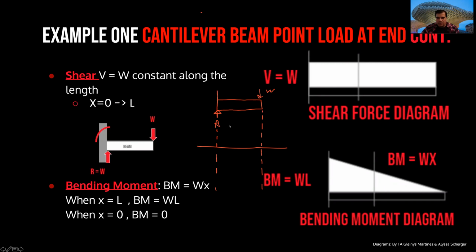And how will the shear force be? Well, if this W is 10, for example, the reaction needs to be 10 because there is only one reaction. Well, I will be starting at 0. Let me change color. I will start at 0. I will go up 10 units, straight, nothing happens, and I go down. Remember, it's like keeping a bank account and looking at your balance. 10 going up positive, nothing happens, 10 going down. This is the shear, and that is what we have there.